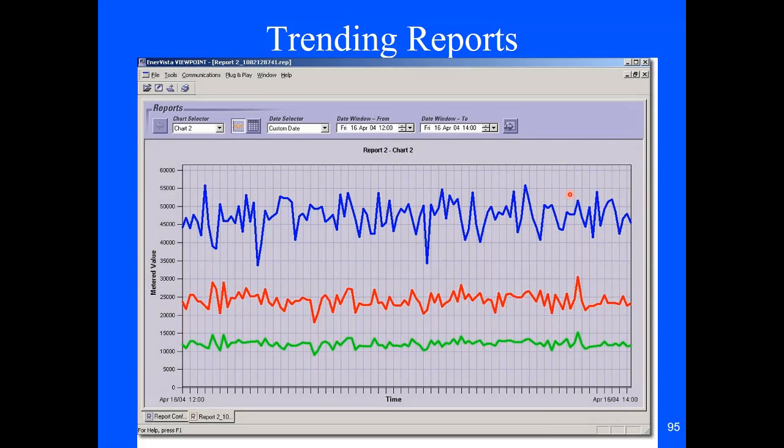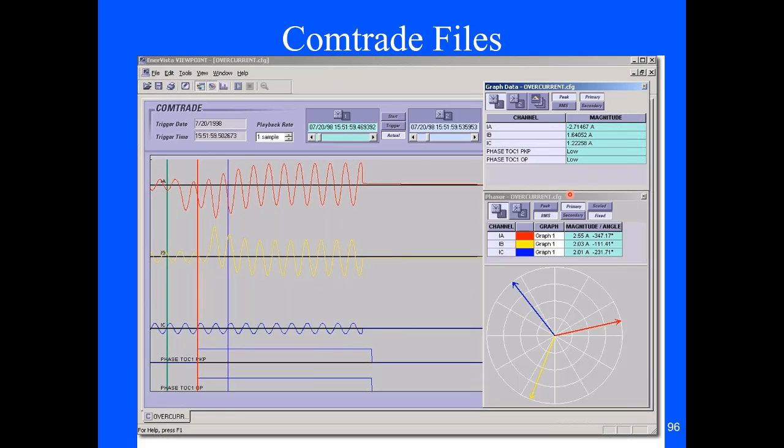So if I want to get the data every hour, what's going on, I can actually see that. I can see Comtrade files. So if there's a problem, one thing I like doing with Comtrade files is don't only trigger on certain conditions, but I like to do cross oscillography. So if any device has an oscillography, I want to grab all of them, because sometimes it's not what tripped, but what didn't trip. So we can see why a device didn't trip, which is kind of nice.